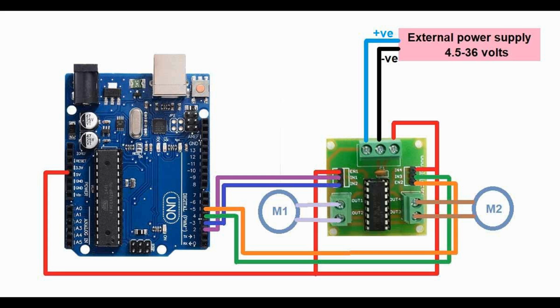Disadvantages: sensorless drivers can struggle with low-speed operation or during startup because the back EMF is too small at those points to provide reliable feedback. They are generally not as efficient as sensor-based systems at low speeds. Applications: used in higher speed applications or in systems that do not require precise low-speed control, such as electric scooters, fans, and high-performance power tools.